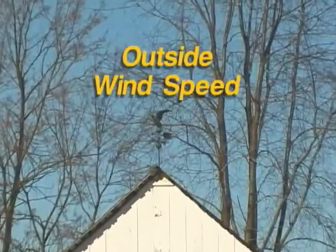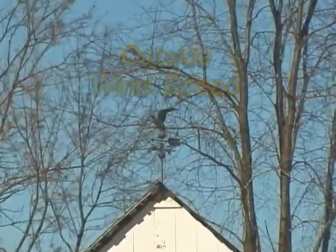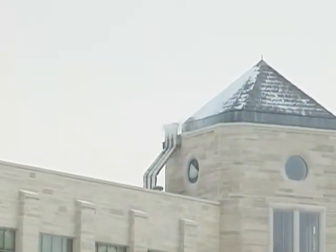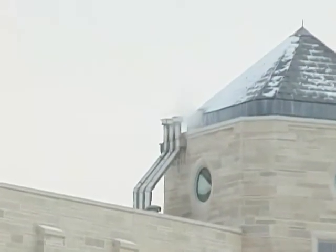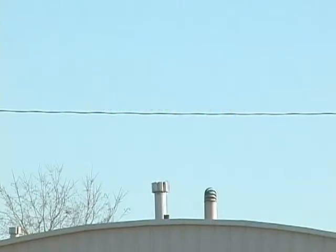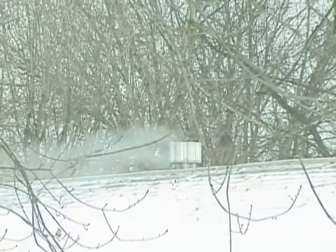Outside wind speed. Generally, the stronger the wind blowing across the top of the chimney, the stronger the draft. Exceptions exist when turbulence caused by nearby roof lines or trees forces a downdraft. Type of chimney cap. In general, a chimney cap helps ensure wind-induced downdrafts won't occur. Some caps are better than others at increasing the draft caused by wind. And of course, a crushed cap will cause friction and reduce draft.